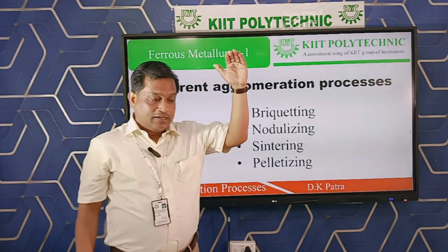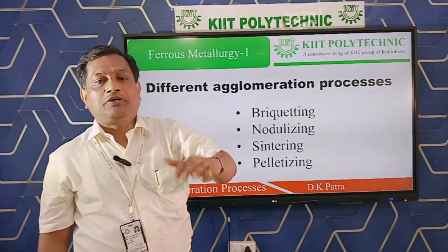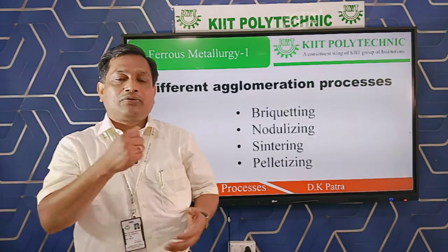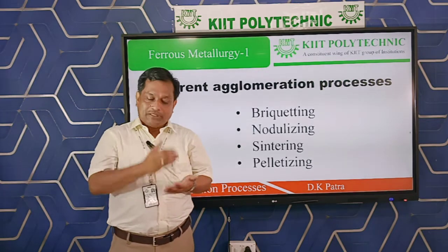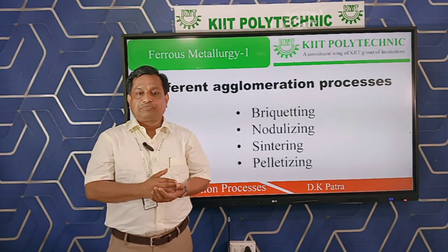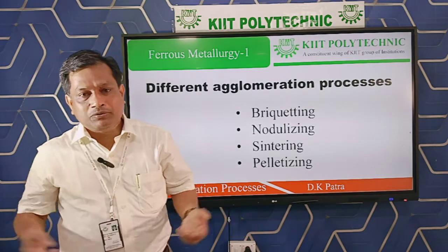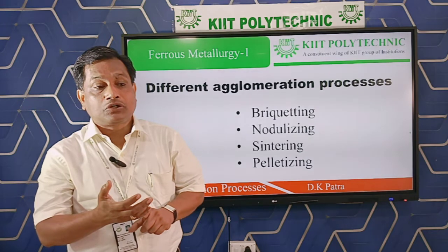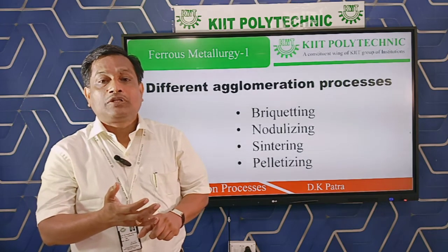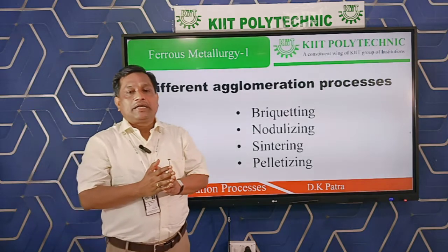Whenever the iron ore enters from the top and travels downward for 20 to 22 meters, it has to react with the carbon monoxide. Now, this is done in a solid state, when the iron ore is in a solid state. As metallurgists, our focus is the economy of the process. Economy is directly related to the cost of production. It is also related to the rate of production.